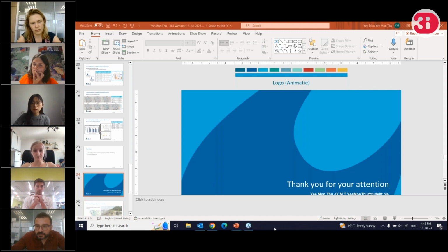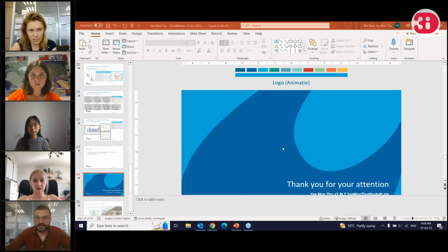Thank you for the question. During the development of the model, we didn't have water level measurements to validate, but what we did was check bigger events, in 2014 and 2018. We check these events to calibrate and validate. We have some pictures of the flooded area and which areas are flood-prone. We also check these areas from our output, to compare the flood-prone area and the flooded area during that event. So we calibrate and validate in this way. Unfortunately, we didn't have measurements for the water level in the city.